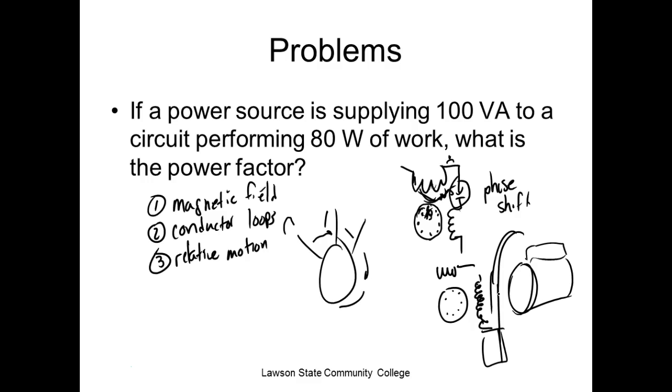So if you got a motor in your HVAC system that just sits there and hums at you, then what does it probably mean? It probably means the start capacitor is going out. Instead of going out and putting a new motor in there, then just do what? And I'll show y'all later on how to check these things. These big capacitors you can check with an ohm meter. You can actually watch them charge and discharge.